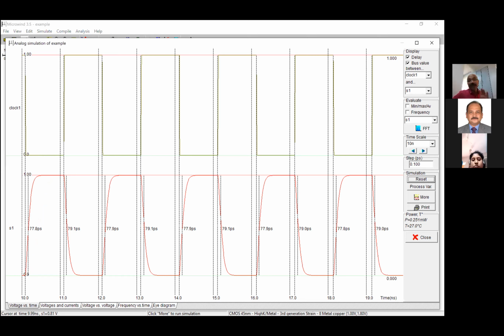Okay, so it's all about the reverse calculations. The current that I anticipated, 3.5 milliampere, was a little higher than my expectations. So I should have done maybe 2.5 milliampere. Then that would have been better. And this is all simple maths, like this is RC time delay. So the charge time constant is 0.7 RC, something you can use to set up this value, okay?